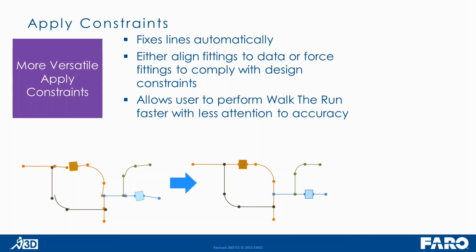We have a number of ways to do it, just reading the data that we have, and then we also have two methods. And I want to explain just briefly the difference between the two methods because they do both have their needs. One is going to be a perfect version of the fittings for your design products. That means all of your 90s are going to be perfectly 90. Center to end lengths won't change, angles won't change, and then you're going to have the times where you need all your center lines to line up, but you need the fittings to actually show their true angles. That's probably most prevalent with cutback and routing elbows, and we actually have a really good way to address that as well.